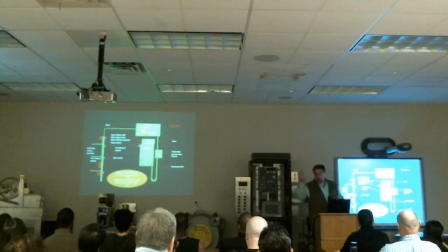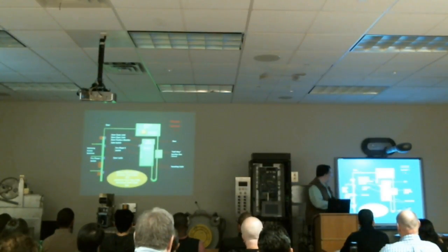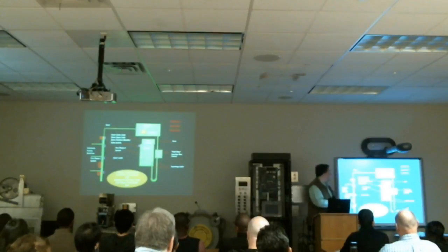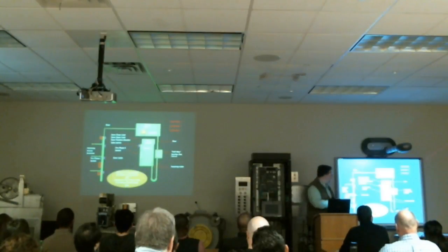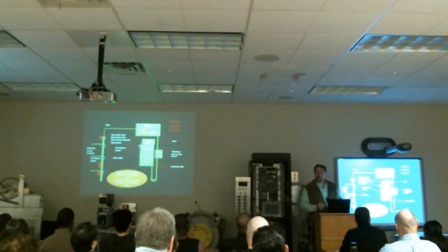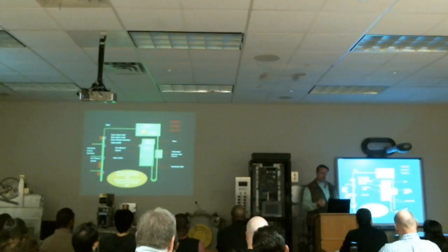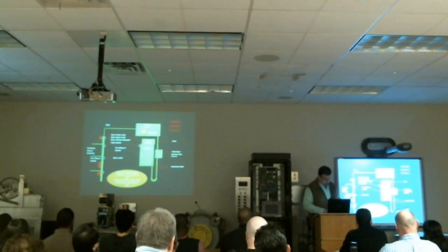Now this is one of the things, when we get more into the sales and estimating end of it, where do these signals actually reside? Some of the controllers that have serial communication terminate on the car top. So these signals stay there and send that information over serial communication. What happens is that you need additional wires in your traveling cable to be able to access those switches from the door lock monitoring unit in the machine room. So one of the things is to verify where these signals are located and terminated. Are they on the car top only? Are they accessible in the machine room? Because that depends on whether the contractor needs additional wiring and a new traveling cable to get those signals back to the control room.